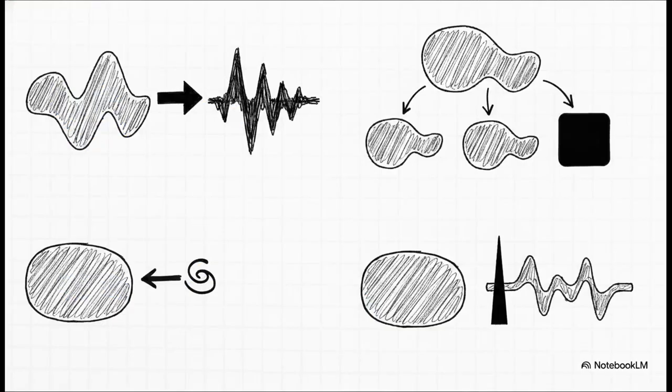Now, before we get too deep, let's quickly lay down the rules of the road for convolution. First, it's commutative, meaning the order doesn't matter at all. It's also distributive over addition. Crucially, if you shift over to the frequency domain using the Fourier transform, that complicated convolution integral magically simplifies into basic multiplication. That is a huge time saver. And finally, what happens if you convolve a signal with a perfectly narrow Dirac impulse? You just get your exact original signal right back.